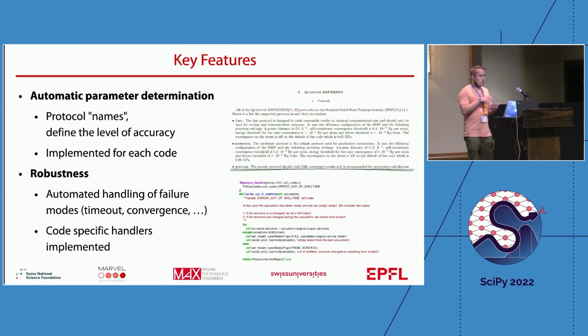This, however, is not enough because it's highly likely, if you've ever run a DFT code for almost any of these simulation codes, there'll be a number of issues you might encounter. Some are relatively basic, like the wall time of your supercomputer was reached, so you have to restart from the last relaxation point. But there are a number of other things, like a self-consistent calculation is not converged, or the diagonalization method crashes, etc. And for each of them, an experienced researcher for that code often knows how to fix the problem, how to change the parameters in most cases. And this can be automated.